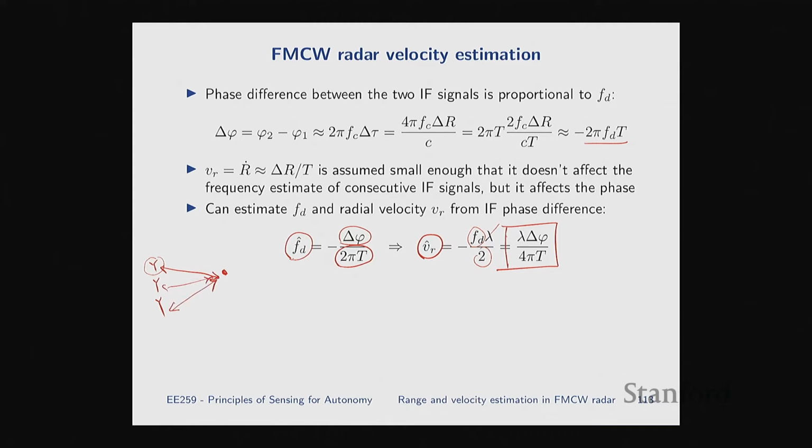That was the question. Well, that's a very valid question, but I think this picture is kind of exaggerated in the sense that the target is shown so close to the antenna plane that the ranges are actually different. When we are talking about far field targets, the target is actually way out here. So we assume that the antennas are so close to each other relative to how far the target is that the range is the same to all of the antennas.